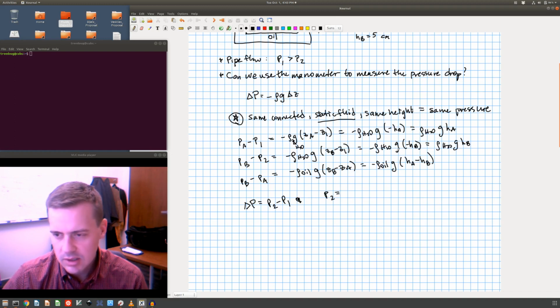P2 is equal to PB minus rho H2O G HB. And I'm going to solve for P1. P1 is equal to PA minus rho H2O G HA.